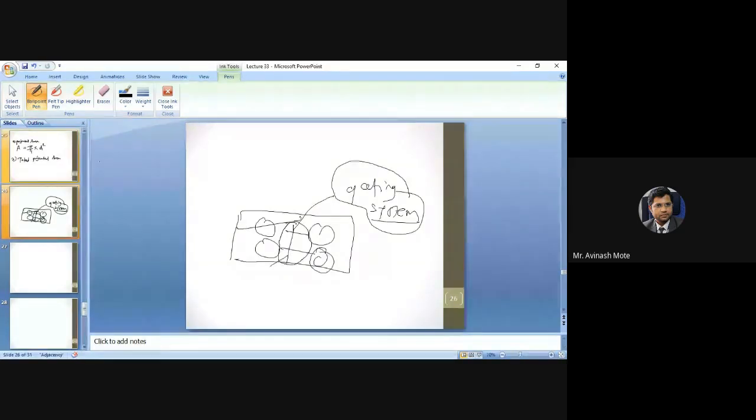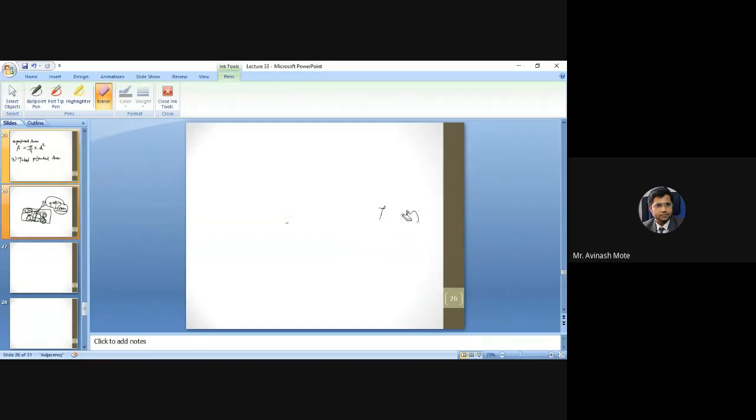So while calculating the total projected area, apart from the area required for this cavity, this cavity, this cavity, this cavity, you need to calculate the area for the gating mechanism also. Not required to calculate exactly, but at least we can have some spare area for that. The general consideration is that the projected area for the gating system will be 10% of the projected area.